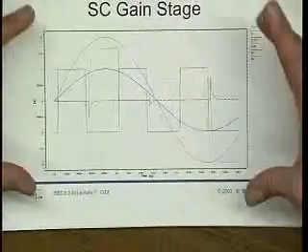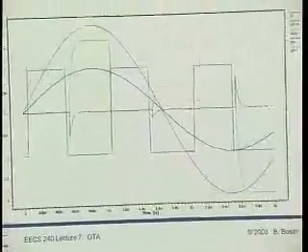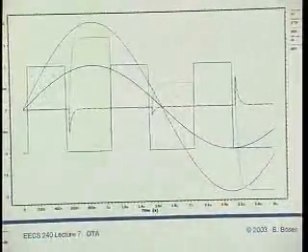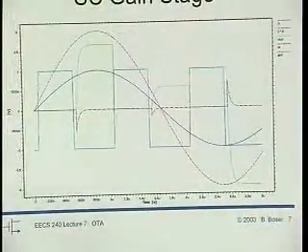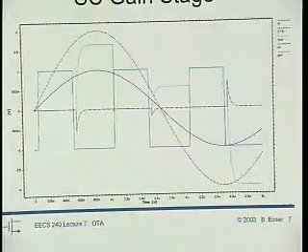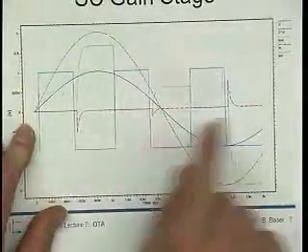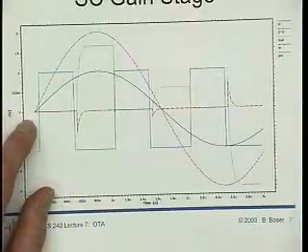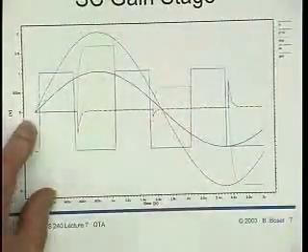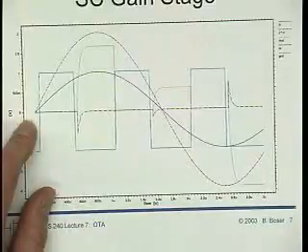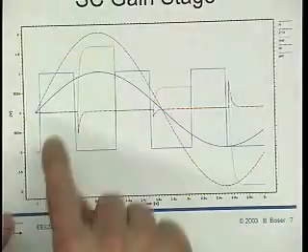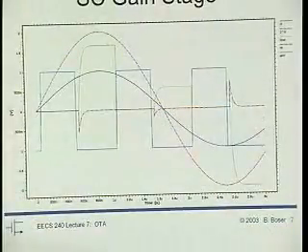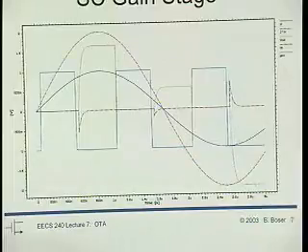So I put this into the computer and ran it through SPICE. I set this so that I would get a gain of 2 just by making CF half as large as CS, right? And so then this smaller sine wave is the input that I actually stuck into my circuit, and then the dashed larger sine wave, that's the output that I would be getting if I had used the continuous time amplifier. Now, because I have this switch capacitor kind of business, of course, I'm not going to get this output. The output is valid only at the end of phase 2, right?